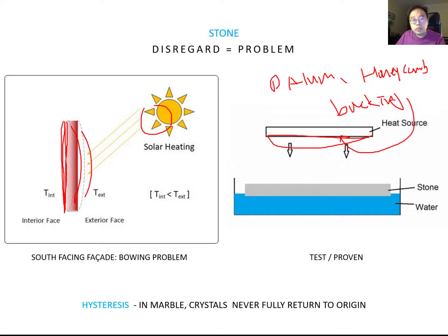And the next one: nowadays many manufacturing companies, especially marble companies, do a lot of testing, which is that the panel has to pass a 40 heating and cooling cycle test. Some manufacturers test 200 cycles. The manufacturer only provides marble panels which pass the bowing test. So the first option is adding the aluminum honeycomb backing panel to the backside of the marble.